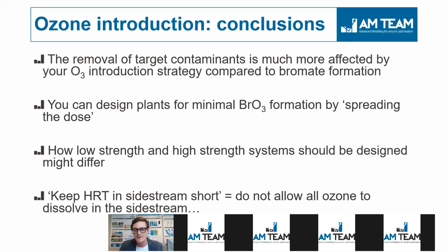Well, actually, you are saying do not allow all ozone to dissolve in the side stream. Because if that would happen, you go very similar to the first column Roberta showed, which is the more drastic case of a very fast transfer of your ozone into the water. So it has to do with the amount of uptake of your water locally, and also the amount of local transfer efficiency you have. This will, in the end, determine your final ozone residual, and your final ozone residual then leads to your local bromate.